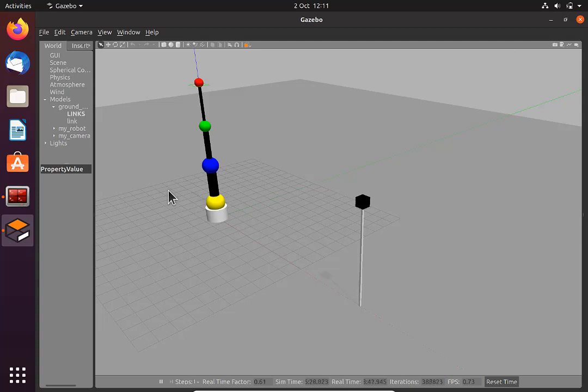So potentially, if you have a problem that Gazebo is very slow, increase your memory for the graphic card in VirtualBox. That should help. But we're not really going to use this environment. This is just to show how the robot moves. You can close this if it's too slow and keep programming. We're not going to need this. I will show you later, but for now I'm going to keep it open.